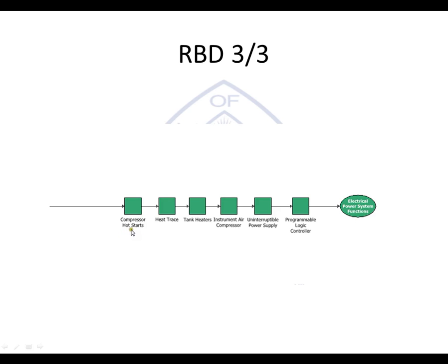The most important on here, in my opinion, would be this guy, the PLC, Programmable Logic Controller. This is basically the brains of the whole site, and if this goes down, it's not possible to control anything on the site, and whether or not that shuts equipment down or it runs away and you have a catastrophic failure, it is arguably the most important part of the site.